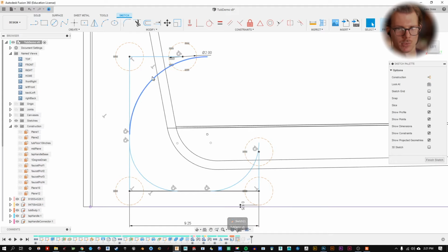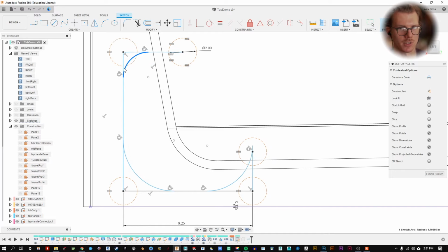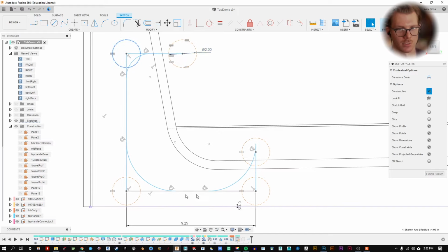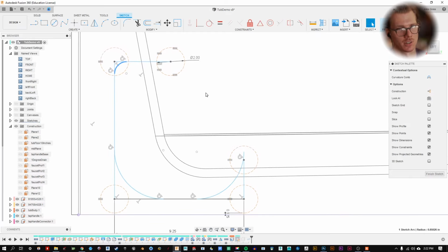So we want to shrink them down, and we also want to give them some meaning, because what we're trying to do is have an arc that this diameter can turn without that pipe command failing. Remember we had some lofts or some sweeps that were failing because the object would be self-intersecting at a certain point. Some things can't make that turn without pinching or getting crushed. Think of it that way if it's like a physical thing. So what we need to do is think about this radius that can actually make that turn. So let's be conservative and just also make our lives easy here.